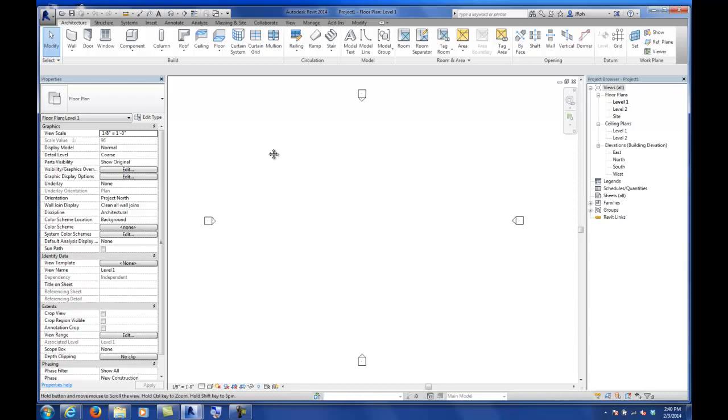And Revit will start to recognize the CAD lines and so forth, and be able to react to them as you bring them in. If you have a 3D model and you bring it in from another file format such as Rhino or SketchUp or these other things, you can bring it into Revit, but once it comes into Revit, it is kind of this object that you can no longer manipulate. And the reason for that is, coming from other file formats, there's basically no parametric information embedded within it. There's no BIM within those files. So basically Revit treats that as a kind of dumb object that comes in that you can just view and maybe change some of the materials. But if you want to do any edits, you have to go back into your other program.